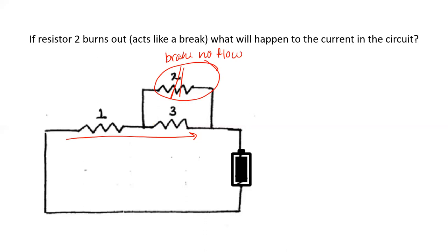Well, because normally extra current could flow through here, that would make this section have less resistance. Now when it goes all through resistor 3, it actually causes the resistance to increase. So the resistance increases and we're going to find there's less current. So we're just using logic to figure out what would happen, and you could go through and calculate. These are really simple circuits. You could build them in the simulator and double check them and prove that that's actually what you see.